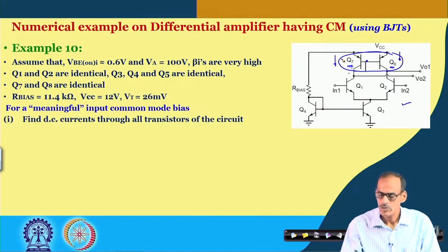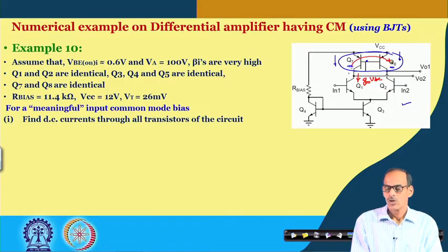In fact, we want this current should also be same as this one from balanced point of view. So, we do not have to put any external circuit to bias it, and in addition to that transistor 7 may also mirror signal current, in case we have say gm into vbe current coming here at the collector. So, that current is also getting mirrored there.